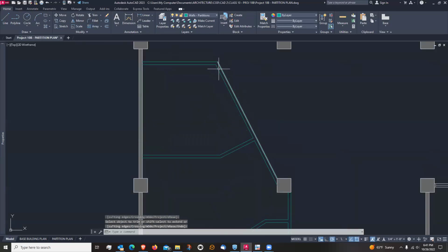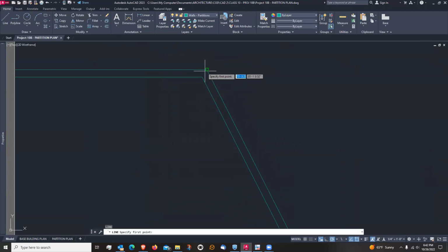So, and then, okay. So over here, I've got a door, and then I've got glazing that goes the full length of the rest of this wall. Let me, you know what, I'll put this door in here. So I'll just draw a line perpendicular, offset 2 inches for a door frame, 3-foot door.